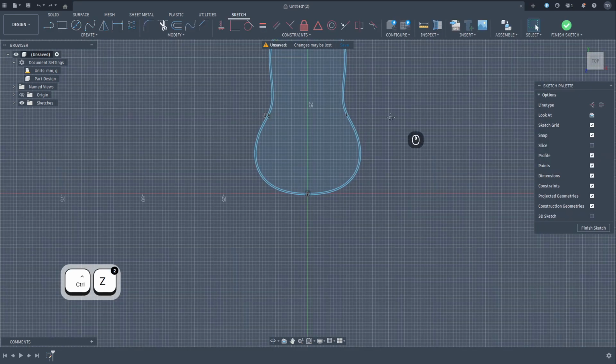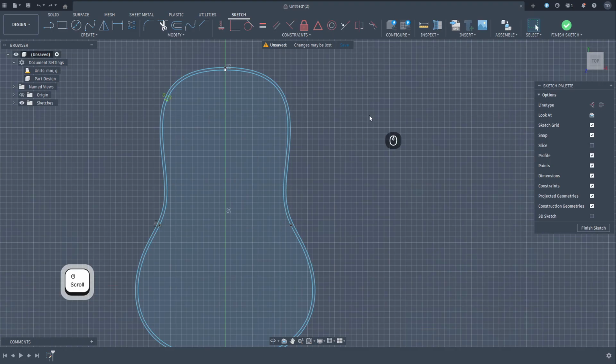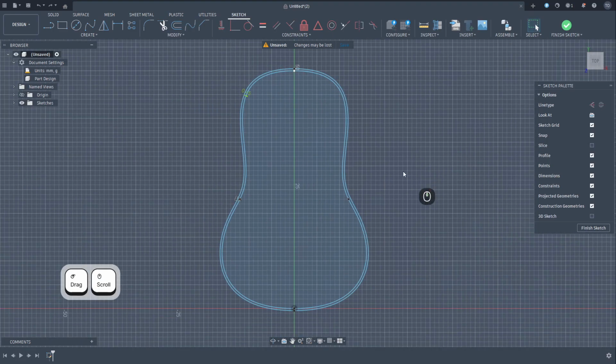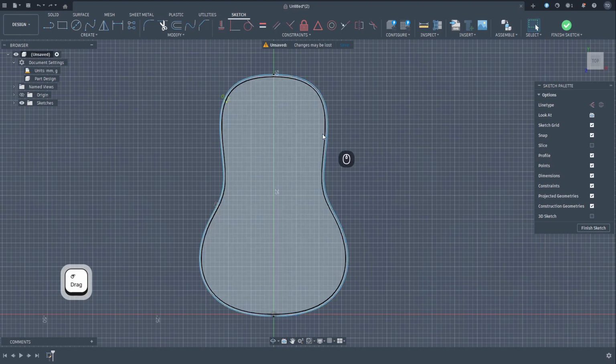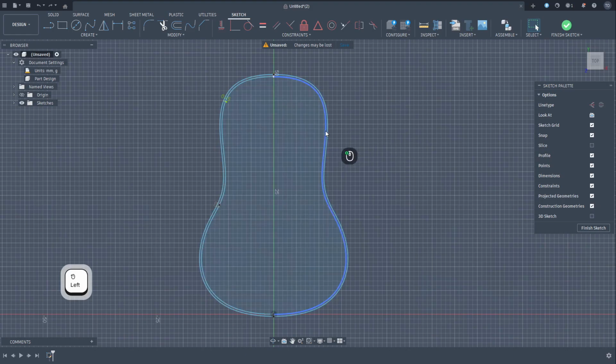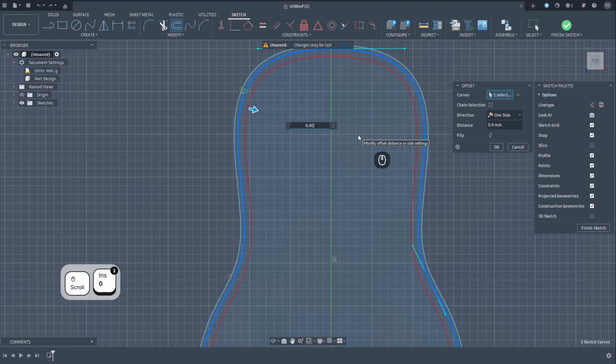And for that, we need to do a few more extrusions. So I usually do this when I create a clay cutter. I'll take the line again, and then you can offset that line as many times as you want. And I will offset this by 0.90, which is double the size of my line width. So I'll keep everything in the same line width.